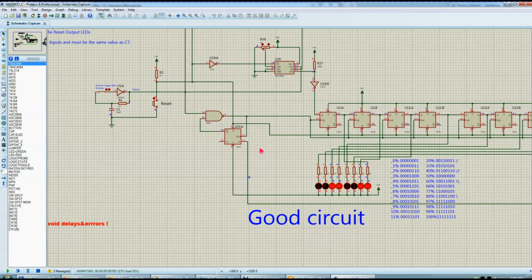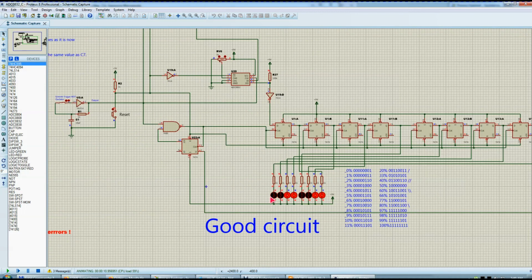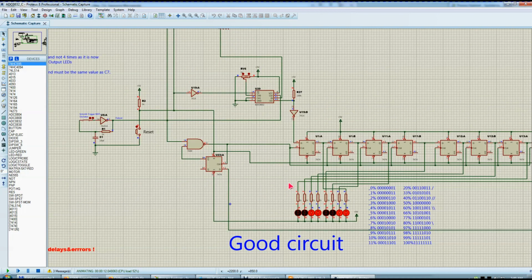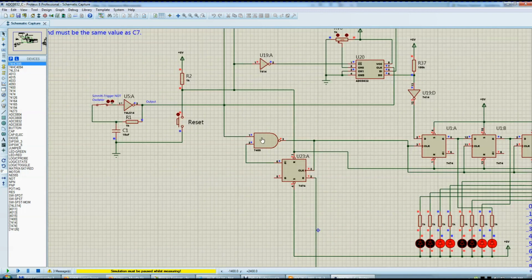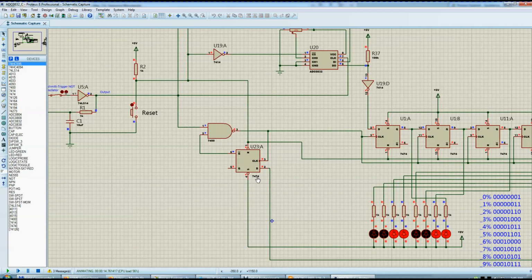If I'm not connecting this circuit, it will pass all this data stream, and it'll be 000 or 1111 everything. It will get into an error, and the correct sequence will not be held in place. That's all this circuit is doing here, and it's perfectly fine with a simple 7400 and not using the Schmitt trigger one. It's absolutely okay. And also another 7474 as the other one, another flip-flop here.